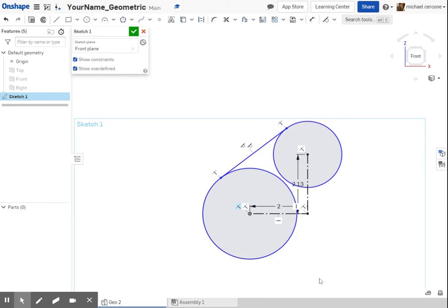All right, so I still really only have 2 dimensions, and that's for these 2 lines here. I now need 2 more circles. One's over here. I'm not going to apply a dimension yet, and one's over here. Also no dimension yet. So if I pull this image up, you can see these are the 2 circles that I've made. I need a line across the 90-degree quadrant of this circle from the origin over, and that goes up, and it intersects at the quadrant, the 0-degree quadrant of the top circle, and it's tangent here as well.